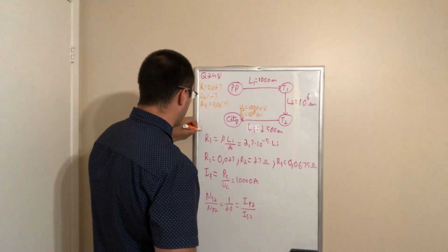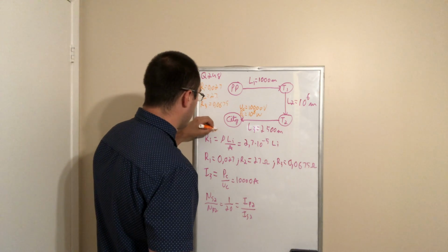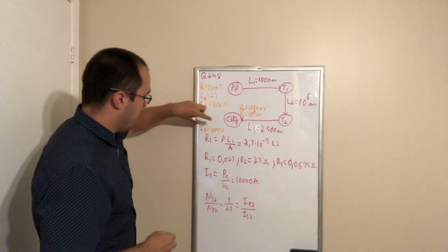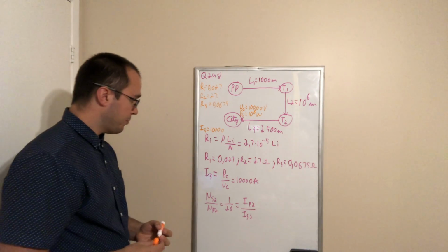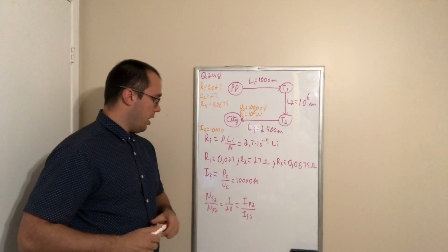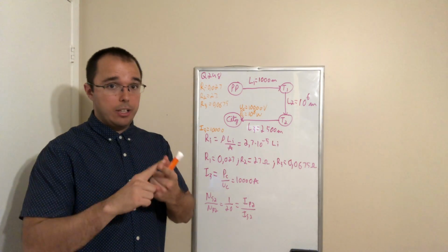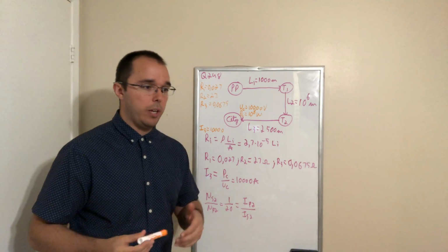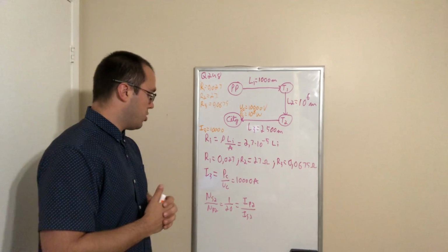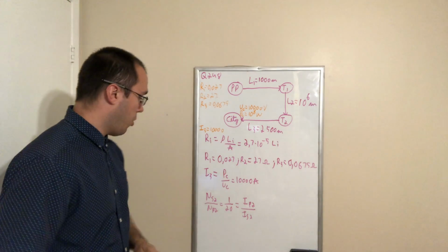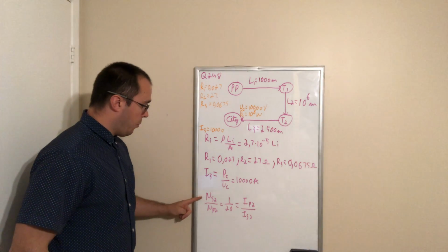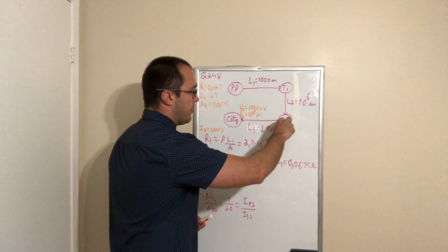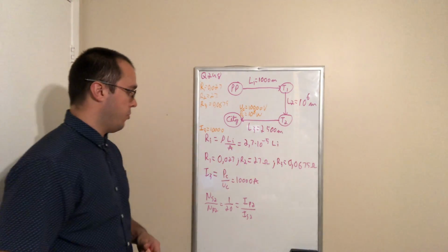I'm going to write it over here. So I3 is equal to 10,000. Now note, I'll omit the unit over here because I'm running short on space, okay? But I3 is 10,000 amp. All right, so we want to find I2 and I1. And basically what we're going to do here to find I2 and I1 is to use the ratio of turns from the transformer. So note, we will start with the second transformer because we already know I3, and I3 is linked to I2 through this transformer over here.